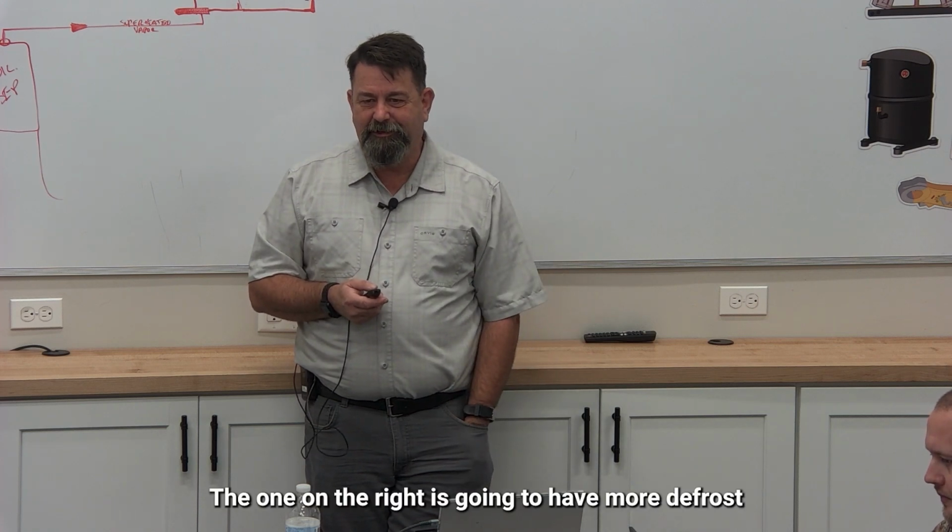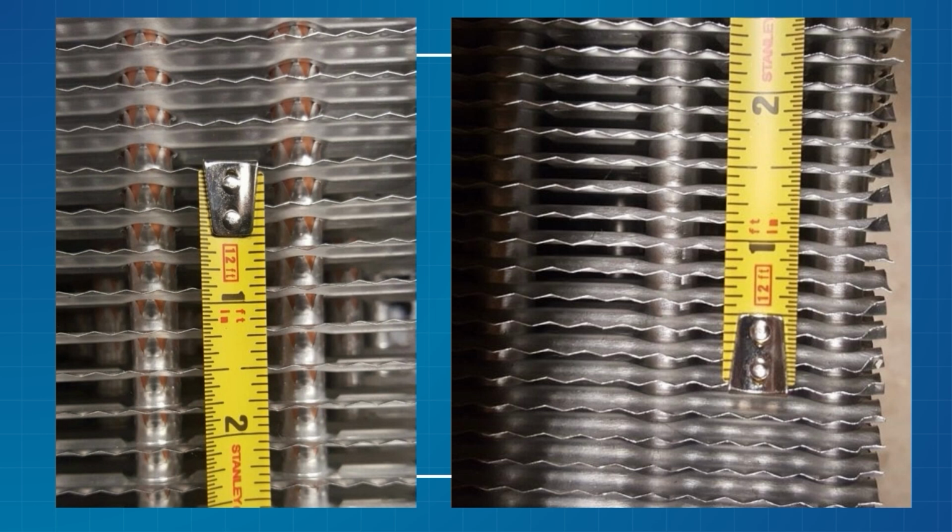The coil on the right is going to have more defrost. All right, so the coil on the right, if they run the same temperature, will require more defrost. All right? What's another possible scenario here? Brandon,